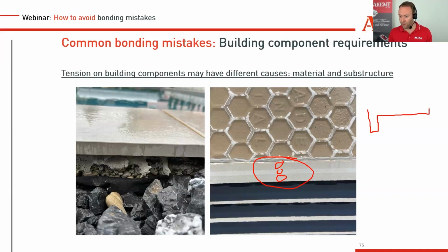we have here this mitred bonding. So now this wants to bend, and maybe in this area or maybe in this side. And if you're not sure if your ceramic or your stone is doing that, we recommend placing here a stainless steel angle, bond it there, let's say with a flexible glue, because then you have steel to ceramic, different expansions.